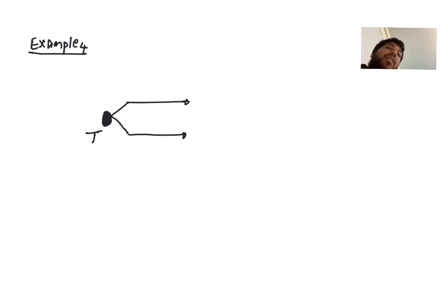Now what happens here is, when the thermocouple junction is connected to a surface at a particular temperature, then obviously with the help of the Seebeck effect we are going to get some output voltage here. So if you look carefully, what the Seebeck effect says is, when the temperature of the joint is increased, then the voltage is going to increase.